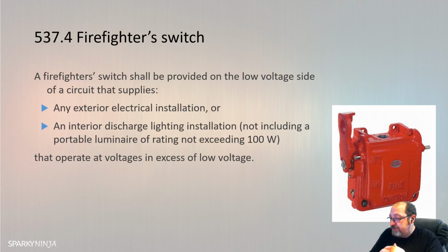For an outdoor, it will be outside the building and adjacent to the equipment, or alternatively, a notice indicating its position should be placed adjacent to the equipment, and a notice should be fixed near the switch so as to render it clearly distinguishable. For an indoor, it will be the lobby, the point where you enter the building.